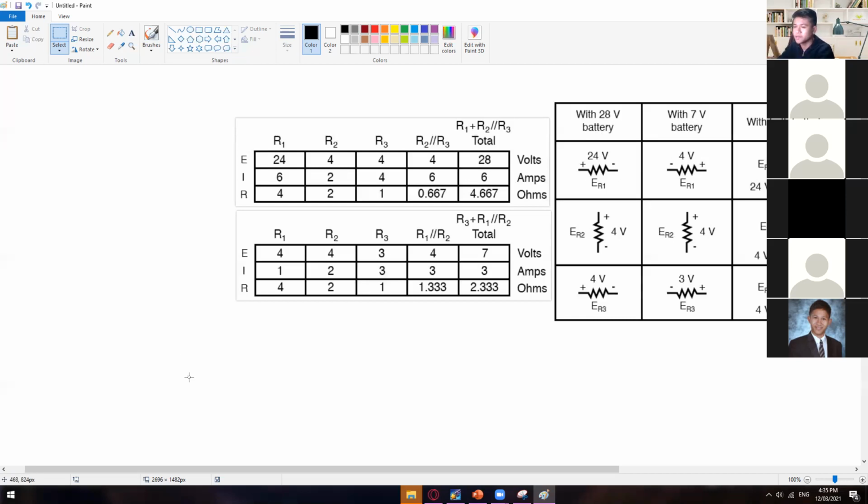So that is why for the 28 volts a while ago, right here, it has a current flowing right here. And for the 7 volts, we also have a current that is flowing right here. So at this point, there is one current that will dominate the entire circuit. In this scenario, the 28 volts, since it has a higher voltage source and of course a current also at the same time, this 7 volts will just be deducted, and we have 20 volts in here, with both batteries.